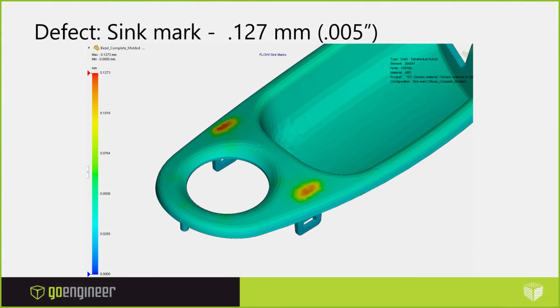So we saw the defect on our part. The defect that I want to correct is my sink mark. It happens because the tabs on the bottom don't have enough draft, and there was a really large radius on the bottom of this face. So kind of some poor part design, but this SOLIDWORKS simulation package would pick this up. So this visual defect would really not be acceptable.